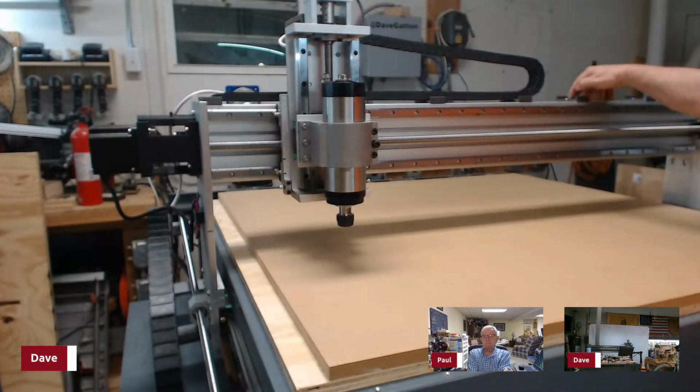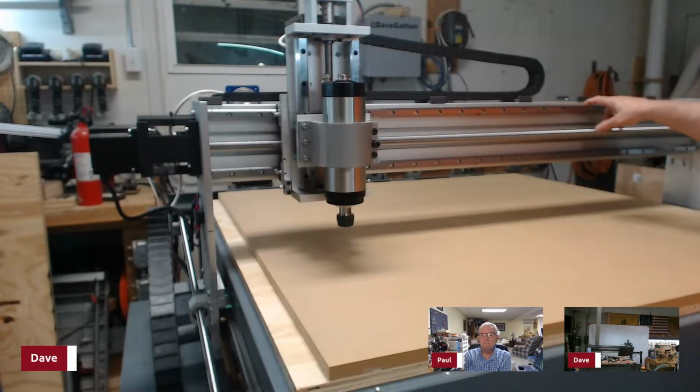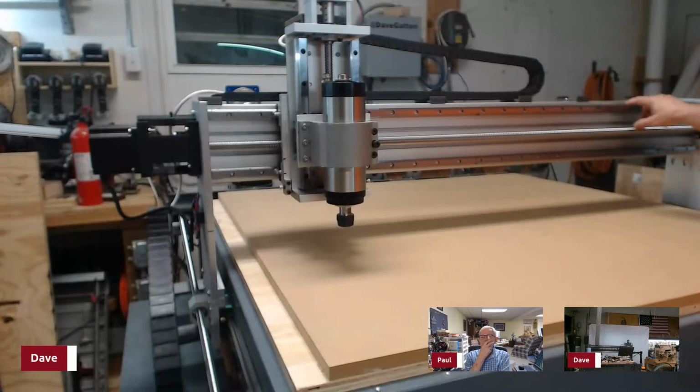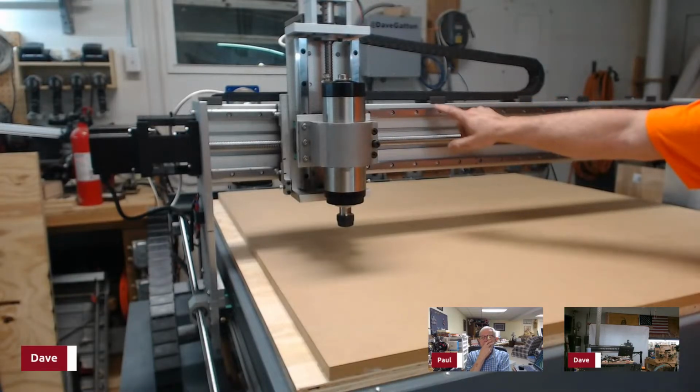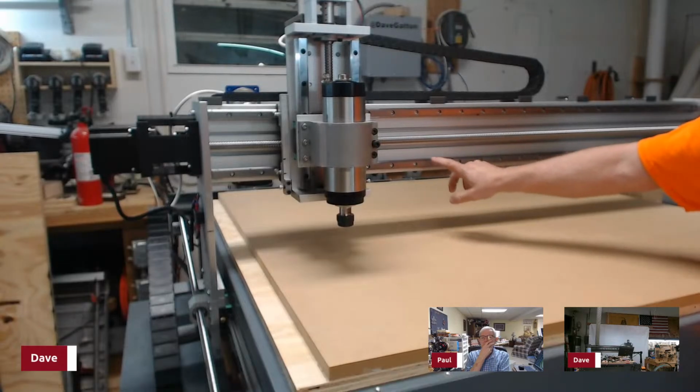They would fasten through these T slots, and then they would hang over a certain amount. Well, I made 3 of them, and you would put them here, and then clamp that like that, and then you would tighten these down and keep moving that thing around so that you get the same distance from the top on this one. But then when you put this one in, you don't tighten these up.